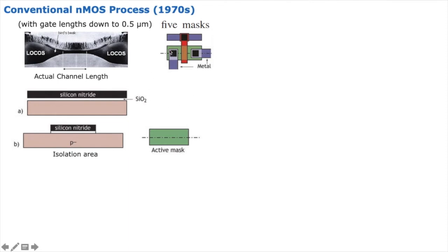In the case of the first mask, remember this is the area that is essentially the size of the device. If you cover this mask here, and then remove the silicon nitride part from the outside, you get this kind of structure. The silicon nitride is still there, this side you remove, so this part is protected.